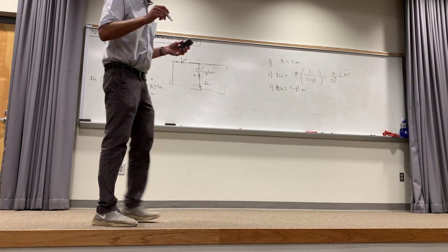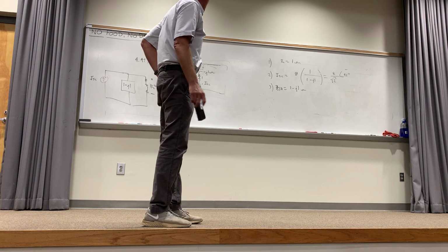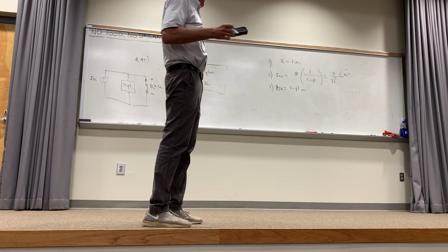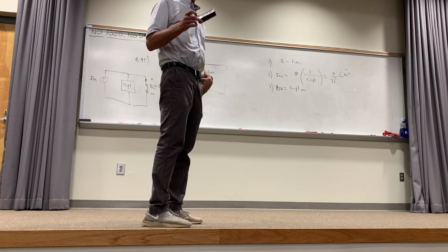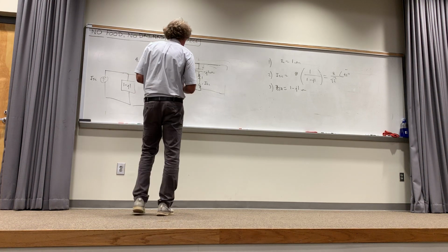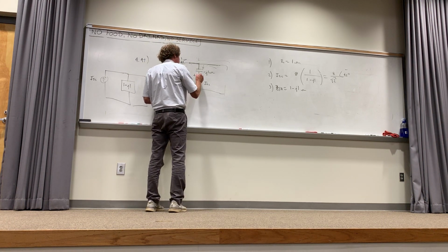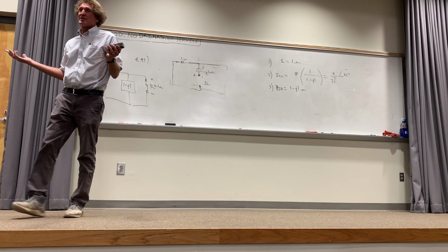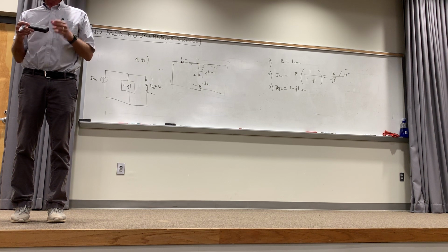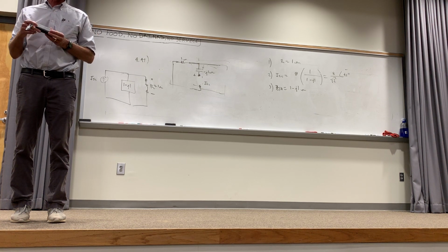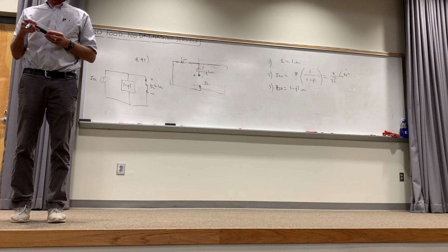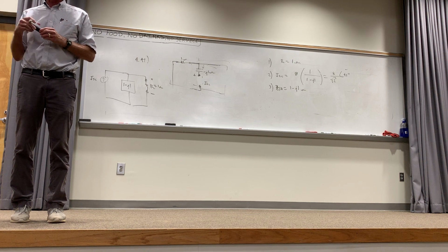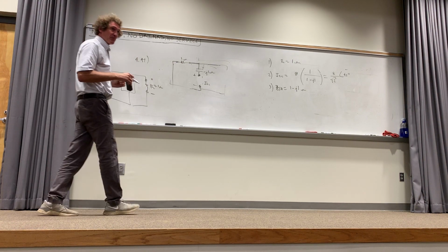Just remember that. Does it matter which way we walk around the circuit when we do it? You can't sum voltages through a current source. I mean, like when you went for Thevenin's, when you went the negative to the plus. Oh, you're saying, this is a good question. He's saying, well, look, you went this way. Will it change this way? No. It's just the same. It's the impedance between the terminals. It'll be the same. It doesn't matter which way you go. Impedances don't have a polarity. Impedance is 1 ohm, period, or minus j1 ohm or plus j1 ohm. There's nothing else besides that, okay?